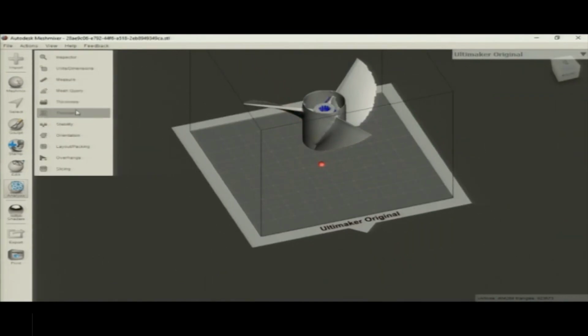Now, there are most important factors to be considered in any FDM print. One is the orientation of the part. Second is your support structure. The orientation and support, as we have discussed earlier, are two defining parameters for the product to be produced.